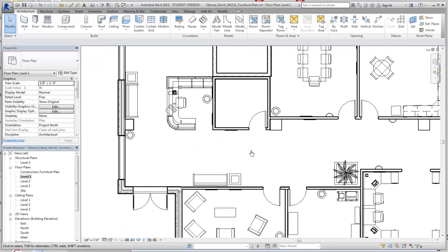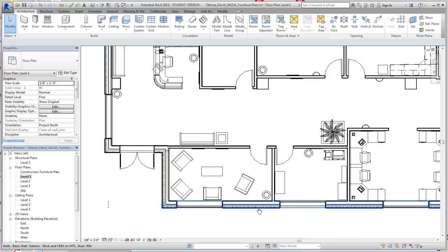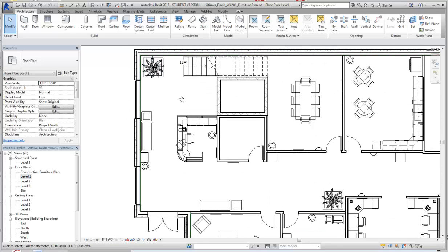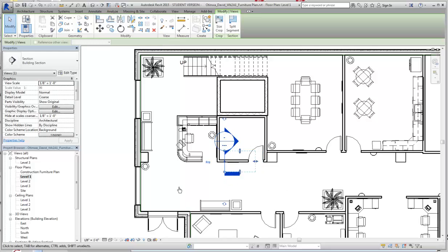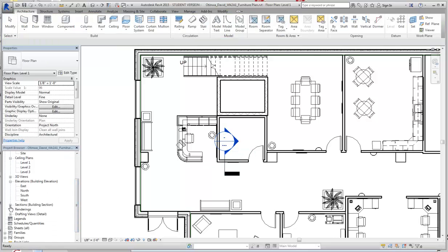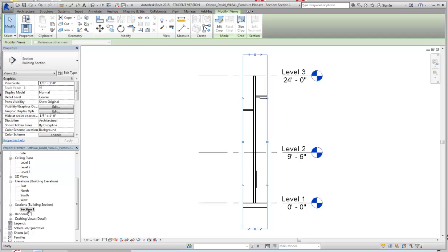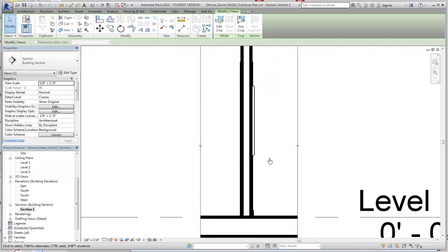this week. And you can see there's a few different wall types in here. We could do the exterior one, or we could go ahead and do an interior. For the assignment, you don't have to do any exteriors. So we'll just work on an interior wall section. What we're going to do is just come up to the section line, bring it in, and then once you've brought that in, over in the project browser, so where all the drawings are, there it is, section 1. So double click on that, and here's your wall section. They've already cut it now.